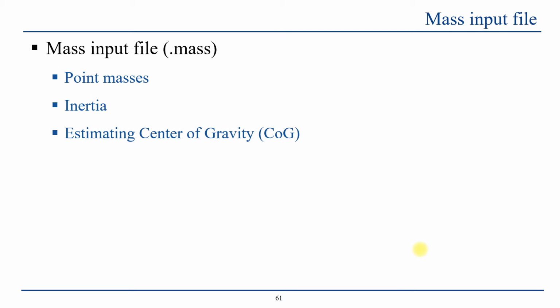And it will help you achieve some estimation for center of gravity, the inertia matrices, and additional information you may need for stability analysis when you're running the mass file, the geometry file, and the run files all together in the AVL environment.